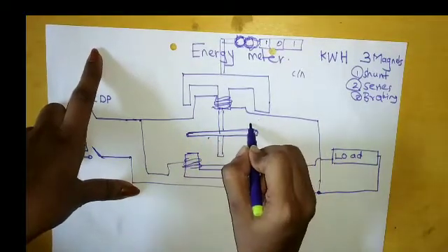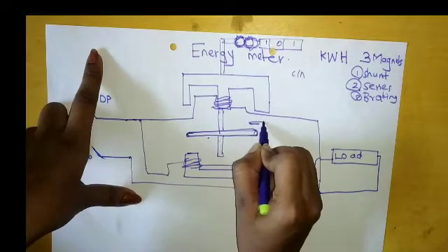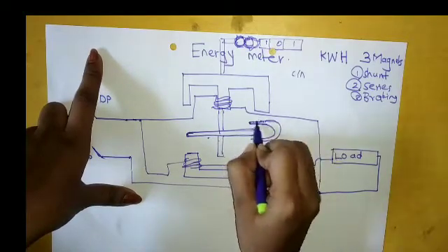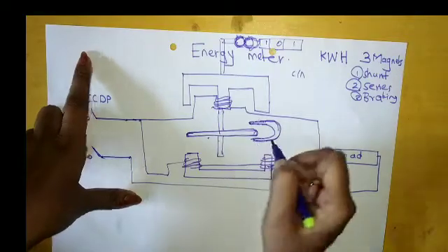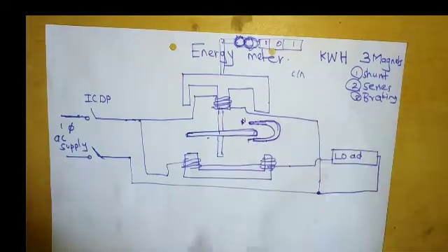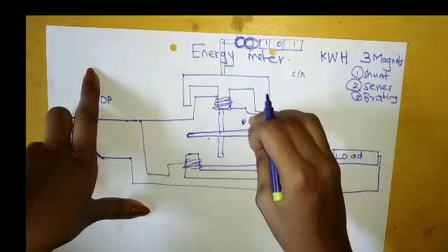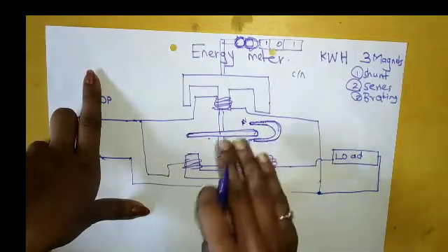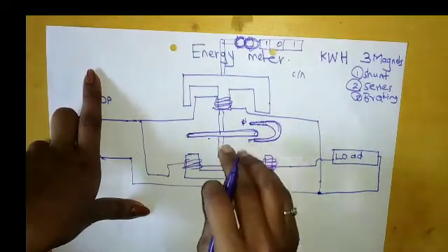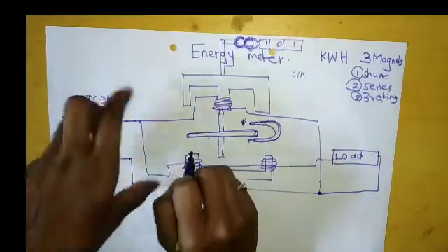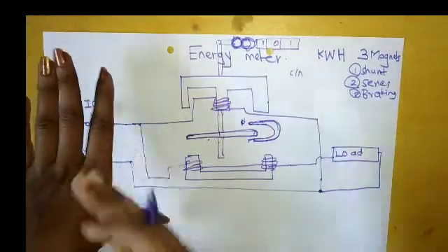So here the third magnet is used, the braking magnet. Now how does it work? This magnet will also have a north pole and a south pole, right? Here the magnet is there, and our disc is rotating. What will happen? EMF will be induced here, that means eddy current will get induced in this disc. This eddy current will oppose the rotation.